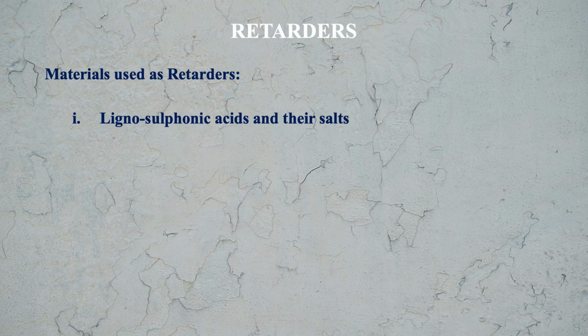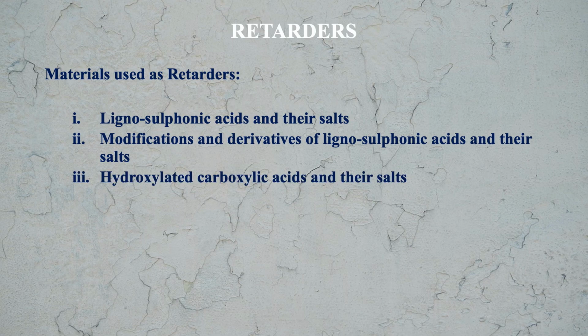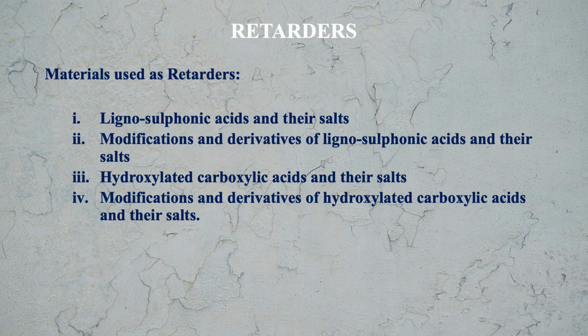The following materials can be used as retarders: lignosulfonic acids and their salts. Another is modifications and derivatives of lignosulfonic acids and their salts. Another material is hydroxylated carboxylic acids and their salts. Also, we use modifications and derivatives of hydroxylated carboxylic acids and their salts. So these are the materials which can be used as retarders.